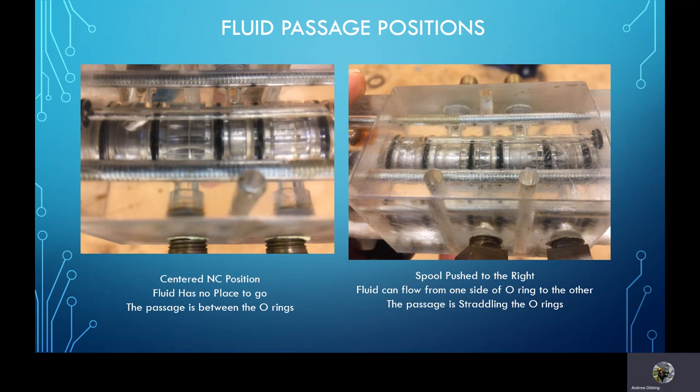Just like in an electrical circuit, every connection point adds a little bit of resistance to the overall resistance of the circuit. Every connection point, spool, valve, gauge, or conductor pipe in a hydraulic system adds a little bit of friction for the fluid, and therefore robs a little bit of power and requires a little bit more pressure increase to get over that obstruction. Right? That's the way I kind of like to think of it.